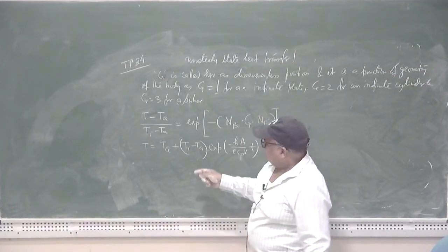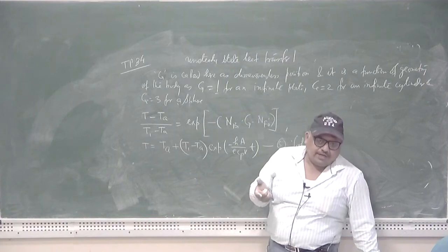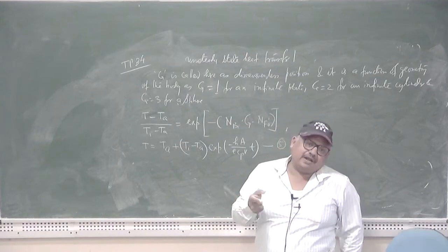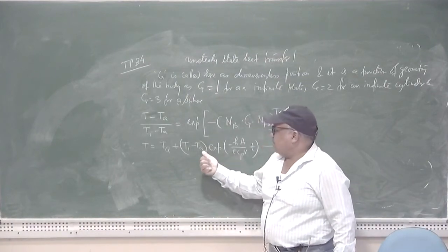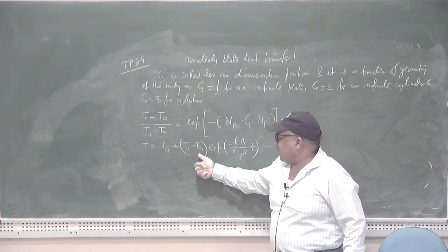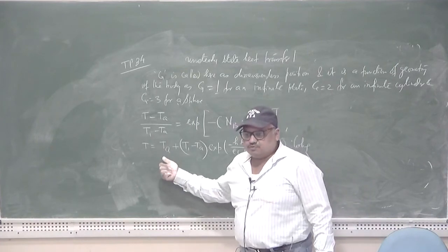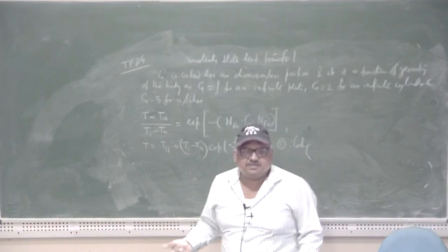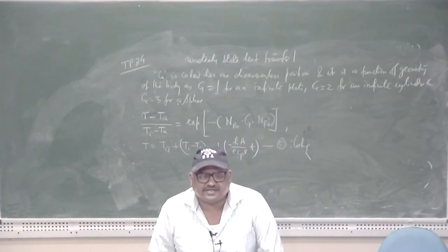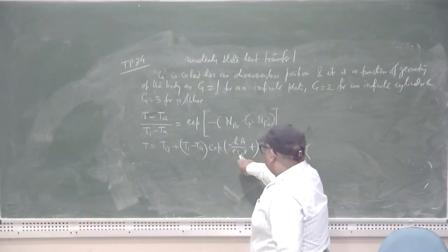That means a body with an initial temperature Ti is subjected to cool in an unsteady state manner in the open atmosphere having the ambient air temperature at Ta. So once the value of Ti attains the value of Ta, that means T minus Ta is equal to 0, after that there will not be any heat transfer, and a steady state condition, or very near to the steady state condition, starts to happen. So this is for the cooling purpose.